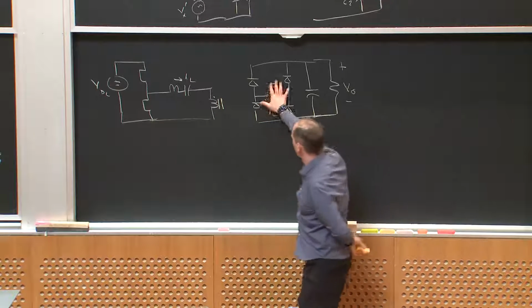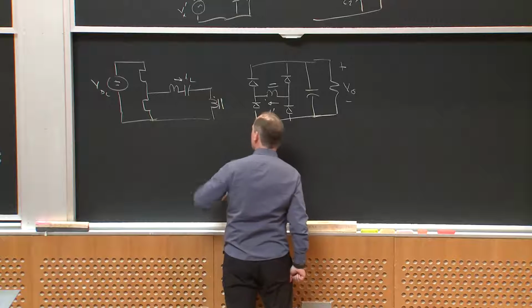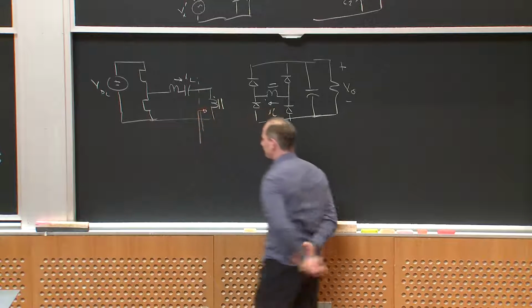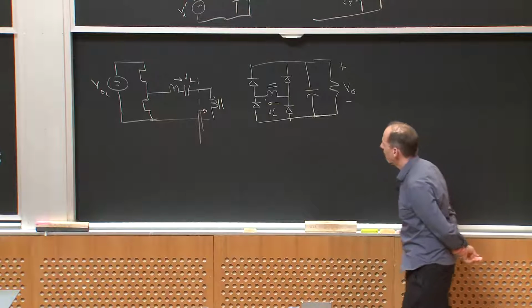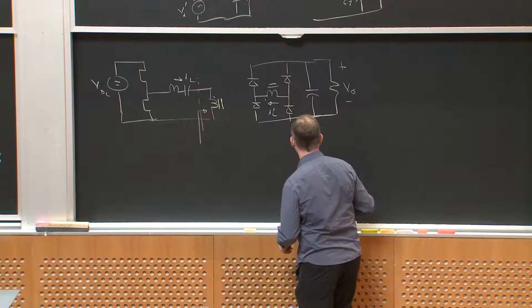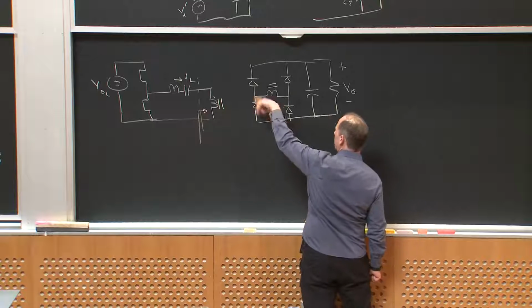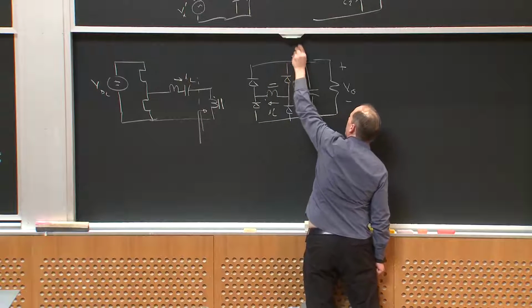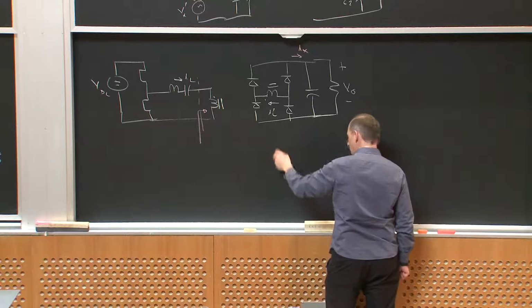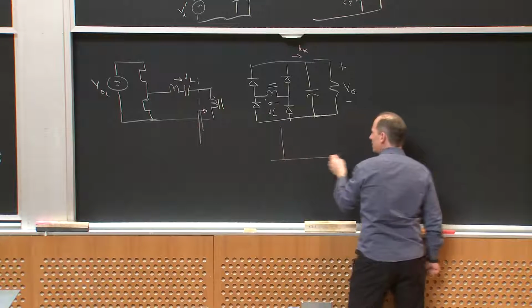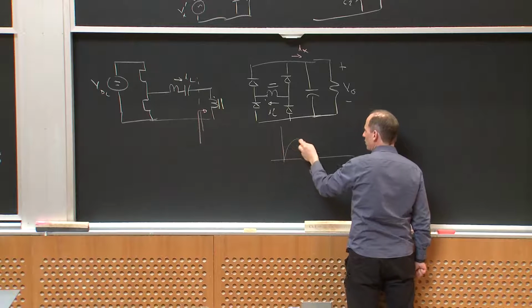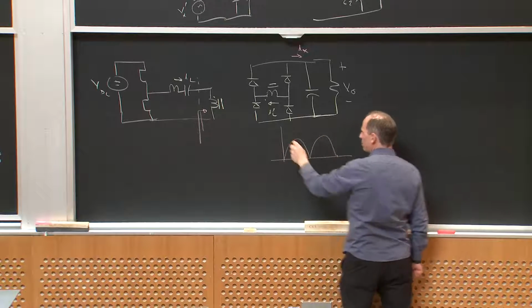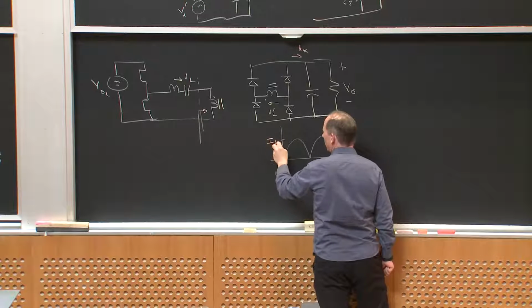What does this network look like, what does this impedance look like looking in here? Okay? Well, if IL is a sinusoid, right, basically I'm going to take a sinusoidal current and then I'm going to rectify it. So then IX here would look exactly like a rectified sinusoid of amplitude, let me call this I sub L, right?